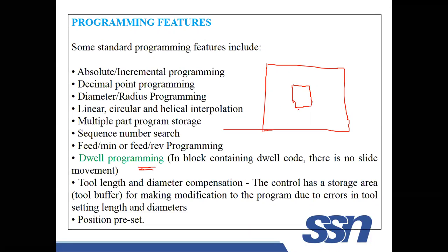So for this, I am making a program like this. Initially, my cutter is at this location, and it will be moving here with a certain feed rate. Means the CNC table is moving. It will be moving like this, and this cutting is done. And I am moving here so that this part will still be attached to the workpiece. Now I wanted to perform the finish operation. The first cut is a rough cut, that is over. I wanted to do a finish cut at this region.